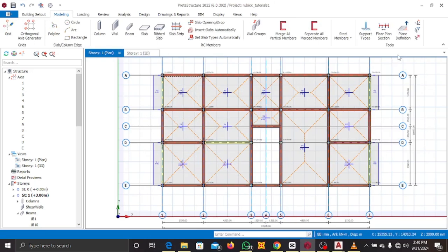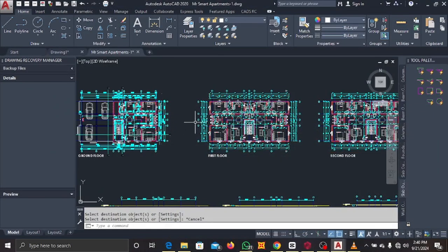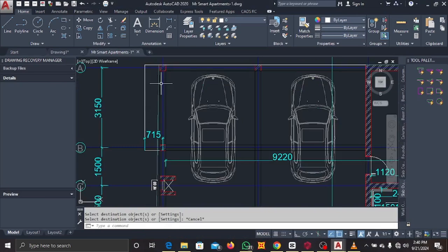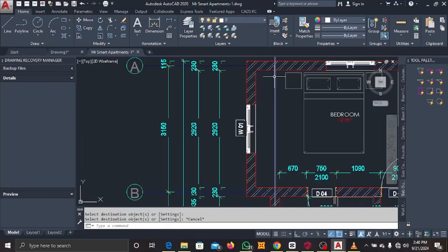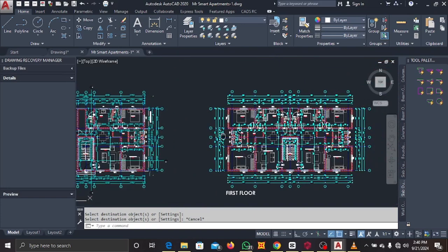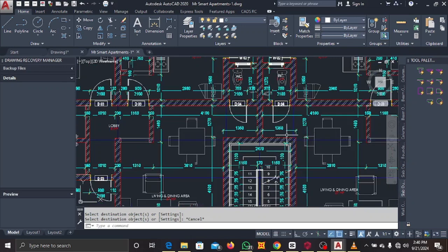If you come to the architectural drawings, you notice that on this wall here, on the first floor, this is where that wall is, and there's no wall here. That's why we are removing the wall load there, so you don't overload your structure. So this is the area where that wall is on the first floor. There's no wall here, there's a cantilever, so the wall comes here. So we're going to move that particular wall load there.